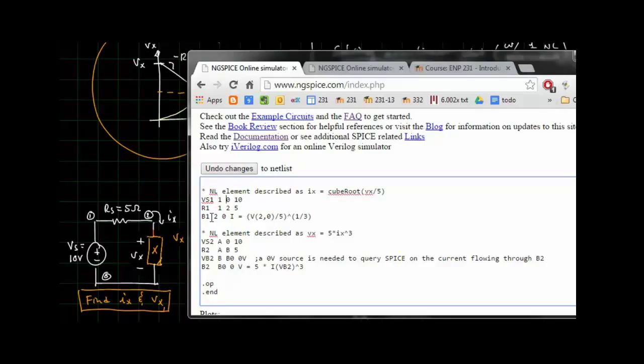Where you wouldn't be able to use it is if you're doing PSpice, like Cadence or OrCAD PSpice. It's based on Spice 2, and they don't implement the B source. But if you're using something like LTSpice, it allows the B source. The B source is really nice.